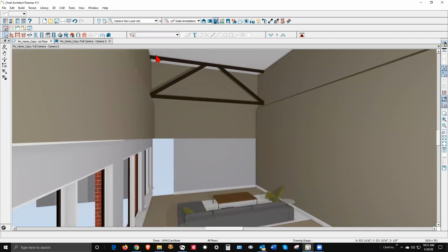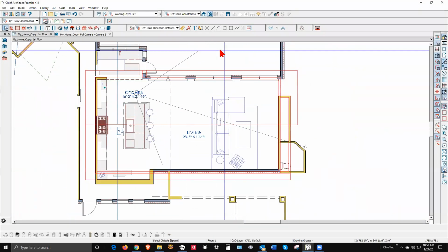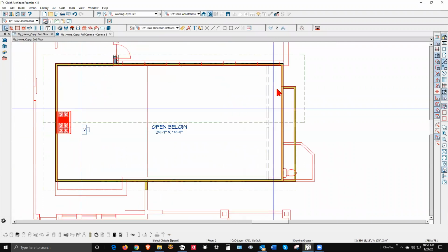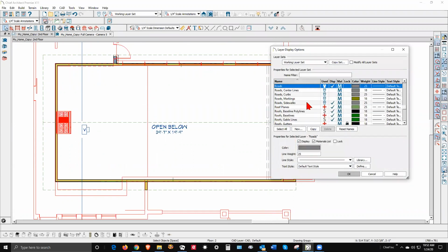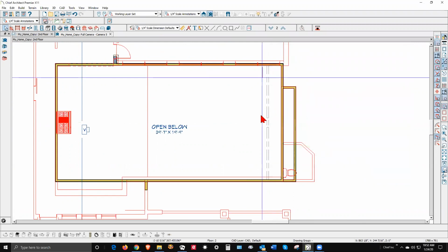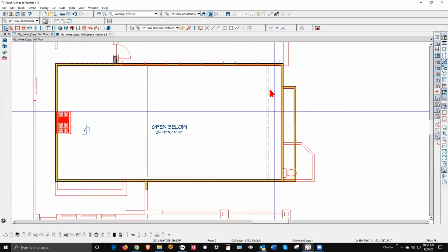Oh yeah, I could put an upright here with a soffit, upright here with a soffit, a king post in here if you wanted, and some other 45-degree angles. And then I would copy those using the copy tool. I know it's not finished, but it's as finished as it's going to get. Now I need to turn the roofs off because I don't want to copy those. So we'll go to the roofs, planes, turn those off. I just want to be able to grab the soffits. I need to press the shift key and click on the wall. Well, it's not working. I have to start over.